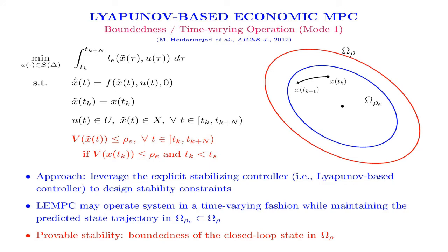However, that general state feedback EMPC formulation does not address issues such as whether or not there exist control actions that cause all the constraints to be met, and does not guarantee closed-loop stability. As a result, there are many variations on the EMPC formulation to try to answer these questions. And the one that we'll be using in this work is the Lyapunov-based EMPC, or LEMPC.